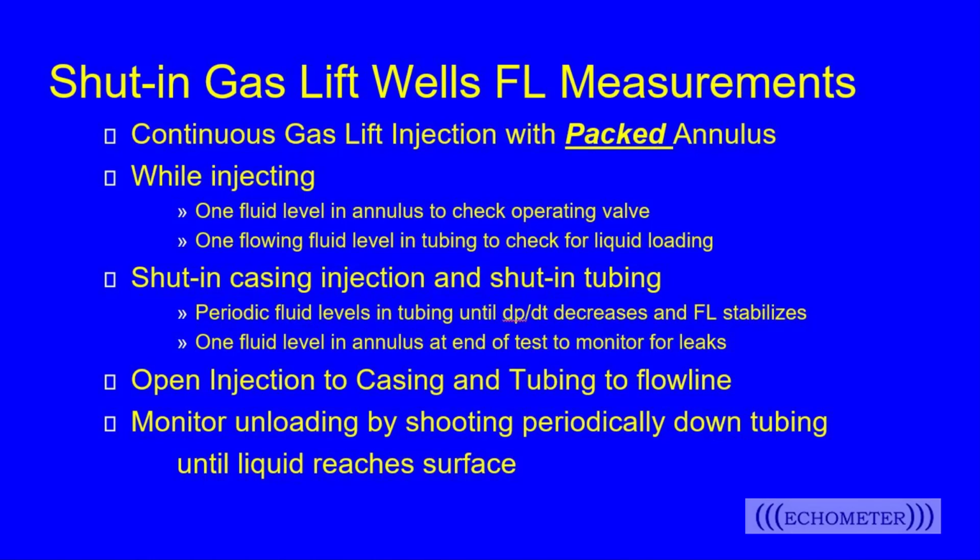Then once we open the injection to the well and we start unloading it, we can monitor that unloading. We can shoot down the tubing at periodic intervals and monitor it to see that the liquid's going to reach the surface and that it truly is reaching the surface, and then unload it.